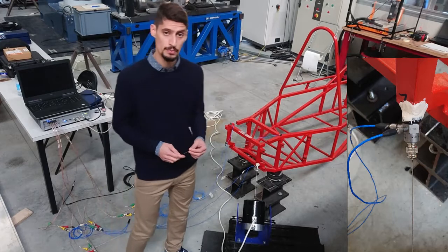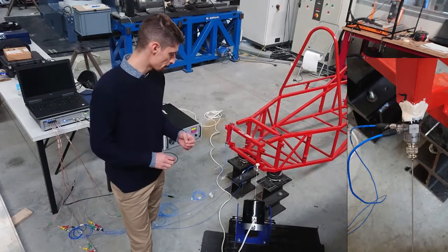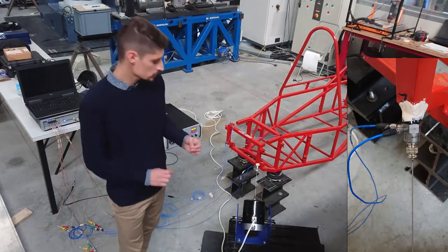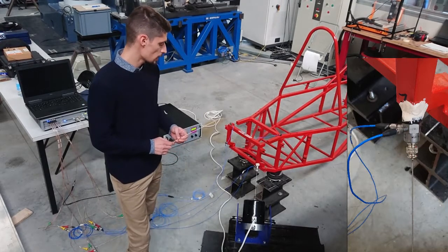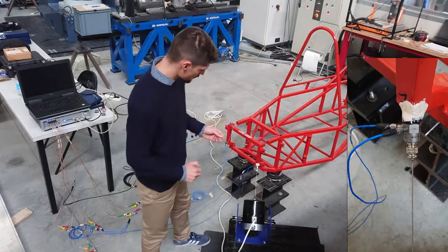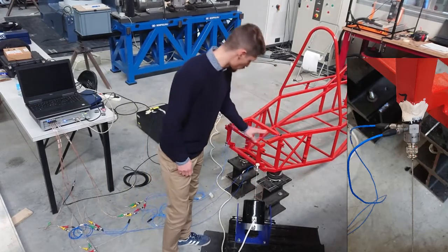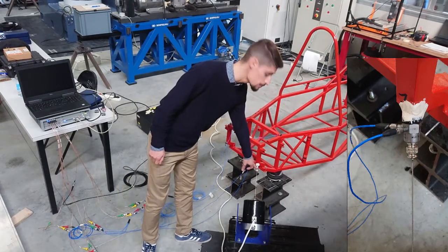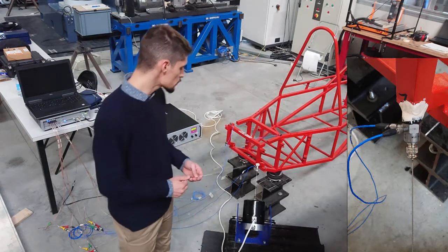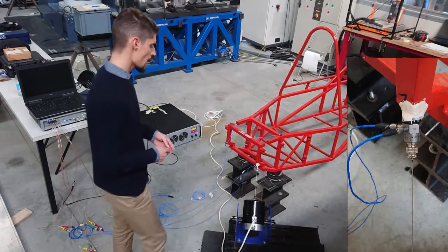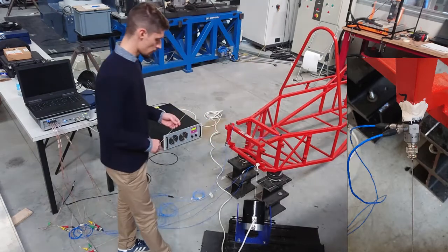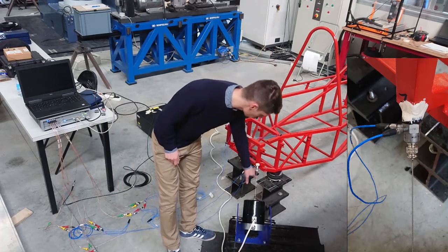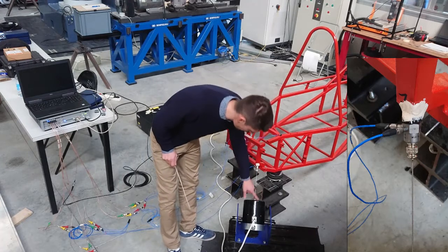And as you know, this measurement is very important, because for estimating the correct FRF during a modal analysis, you must measure the driving point. And in our case, the driving point is the point that connects the shaker to our structure. And you can do that thanks to the impedance head, that measures force and acceleration at the same time in the same position. You must know that the impedance head measures the force and acceleration along the actual direction of the stinger, so along the actual direction of the shaker.